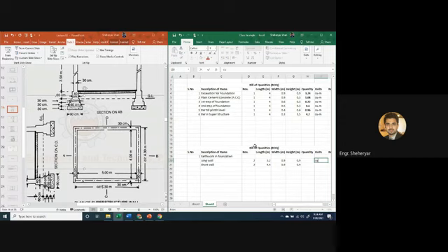Units will be cubic meters. And here the quantity will come. So let's calculate the quantity first. This quantity will be length multiplied with the width multiplied with the height. This is the quantity of one long wall multiplied with the number of long walls, which is 2. So it will give you 8.424. And if I repeat the same calculation here, this is giving me 7.128.